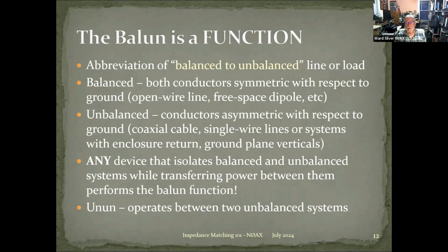Unbalanced means the conductors are electrically asymmetric. Coaxial cable, typically the outside conductor, the shield, is connected to the system ground reference, either through enclosures or directly to a ground plane or a panel.